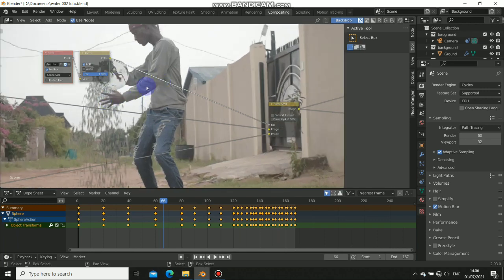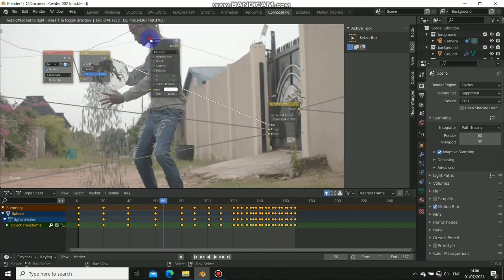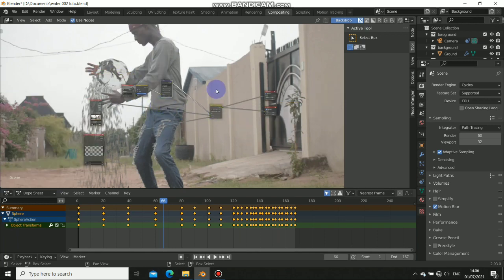But you can do something else by blurring this a little bit. Use a blur node with a filter. Go to blur, plug it here, then choose Fast Gaussian. Now blur the X and Y a few times. 2 is okay for now. You can see that everything should be working fine.